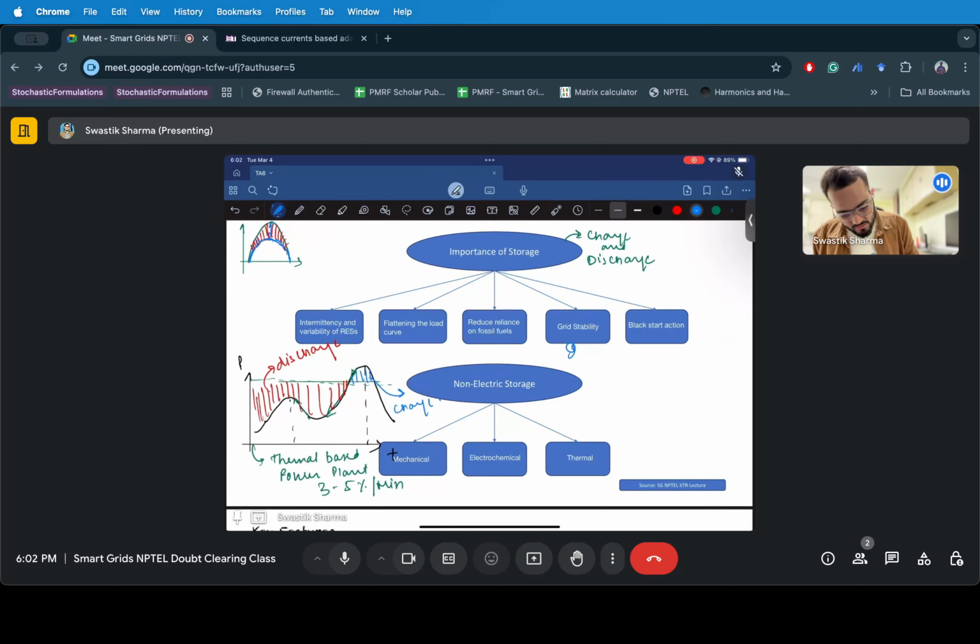Because they're inverter based resources, you can use them to exploit PF control or QV control, right? So you can do that to have a better frequency support or voltage support for your distribution system, or anywhere where it is planted.